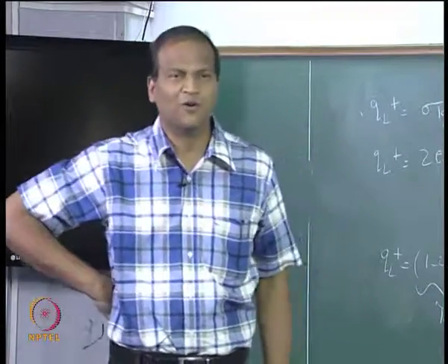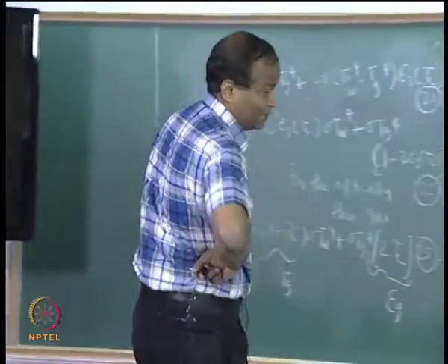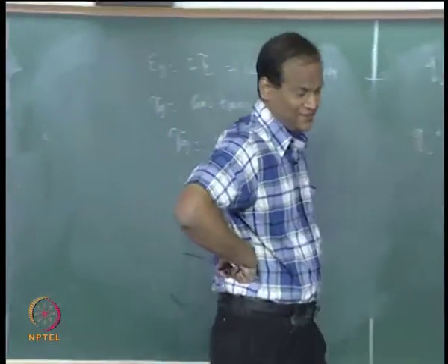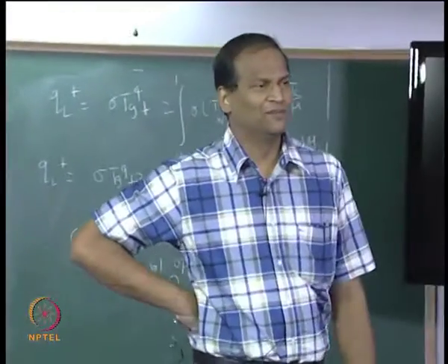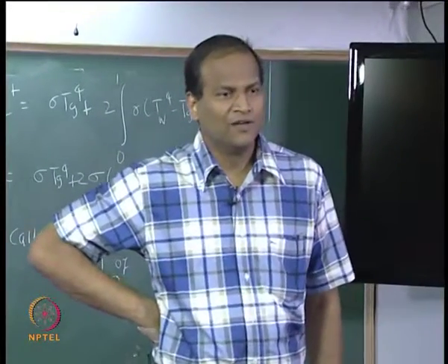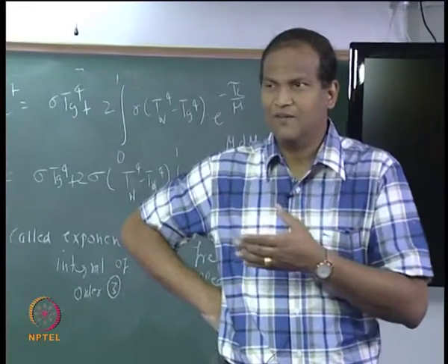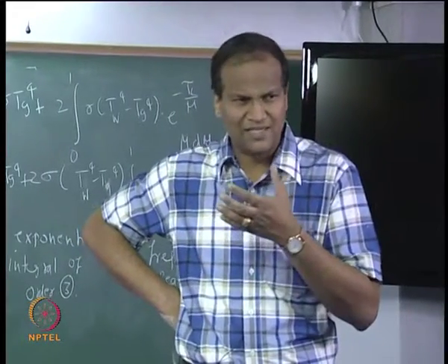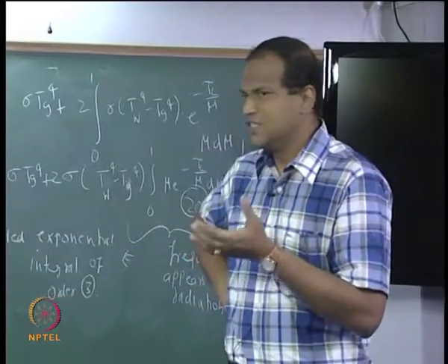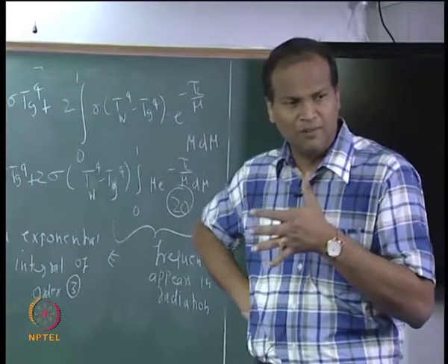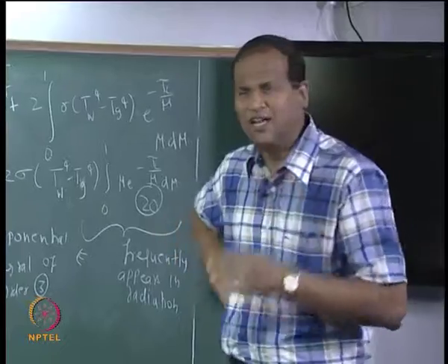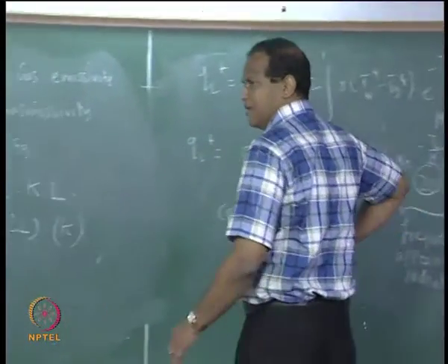Now comes the killer stroke. For all this, the goal of anything is to finally simplify, right? Now at the end, we are able to define equivalent gas emissivity, which consisted of 2 parts, 2L into kappa. Intentionally I put 2L within brackets and kappa within brackets.